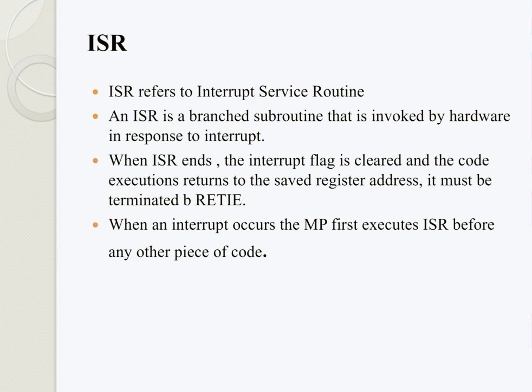ISR. ISR is the short form of Interrupt Service Routine. An ISR is a branched subroutine that is invoked by hardware in response to an interrupt. When the ISR ends, the interrupt flag is cleared and the code execution returns to the saved register addresses. It must be terminated by retfie. When an interrupt occurs, the MCU first executes the ISR before any other piece of code.